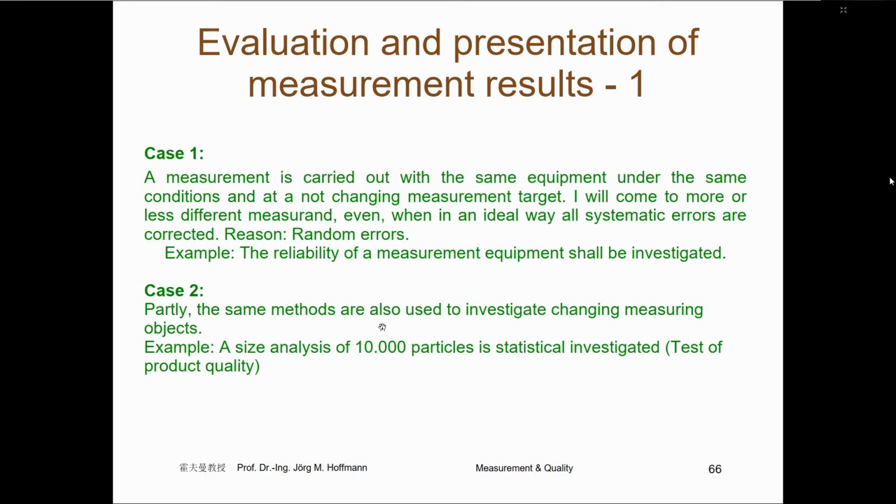In the practice, we say that the error of the device must be round about 10 times lower as the expected changing of the measurement target, your things, what you would like to measure. I have an example here, a size analysis of 10,000 particles is statistically investigated, test of product quality.